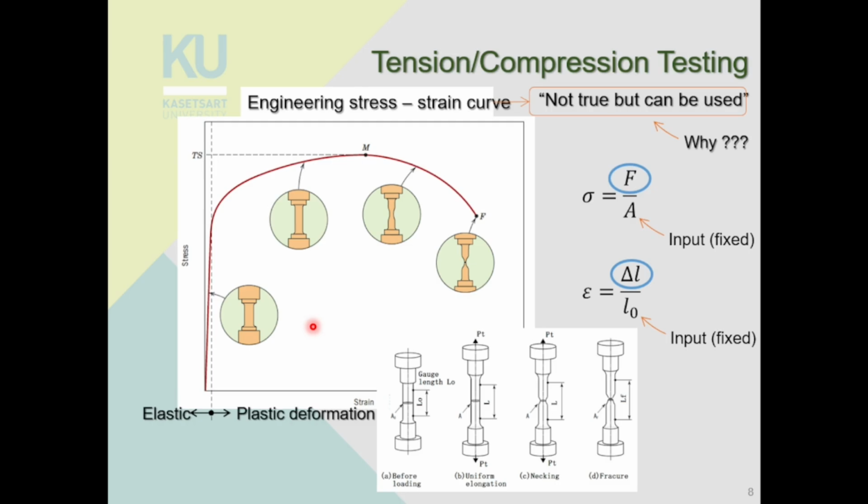And in this graph, the property that is interesting is the elastic limit here, right? Or we would call that the yield strength of a material. The yield strength is the stress that we need if we want to deform it into the shape that we want. For example, if you have a sheet metal and you want to form it into, say, a car door, you have to apply stress higher than the yield strength or the elastic limit of the material, so that piece of steel, that sheet metal, will stay as a car door. It doesn't spring back to that original sheet metal, right?